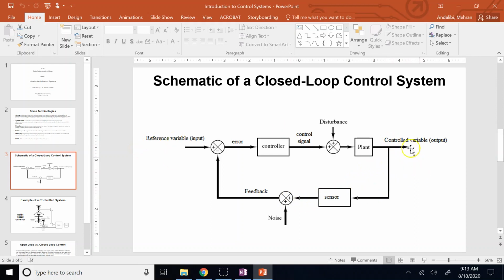So you bring 70, you bring 75, and then subtract. Clearly, 70 positive, 75 negative, when you subtract, you get the error, which is the difference between the desired output or the reference variable input, that's the same thing, minus the actual output, right? So it's always desired minus the actual.